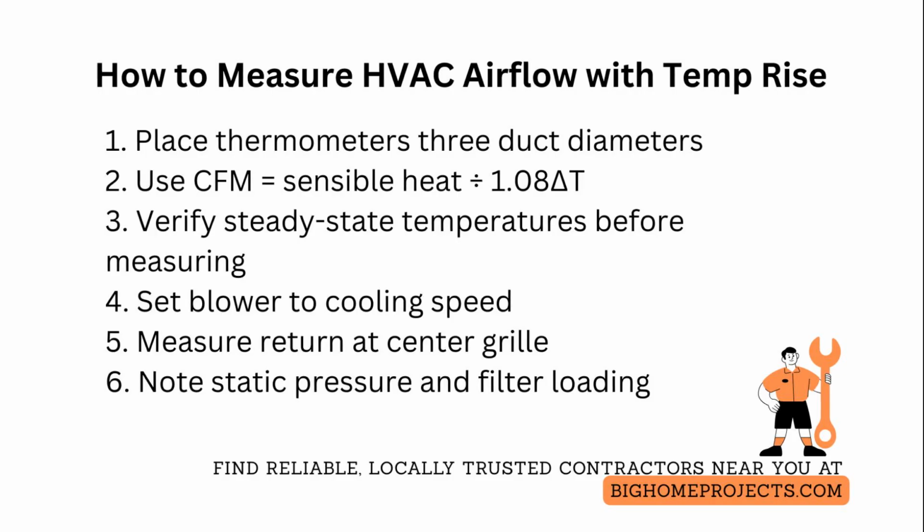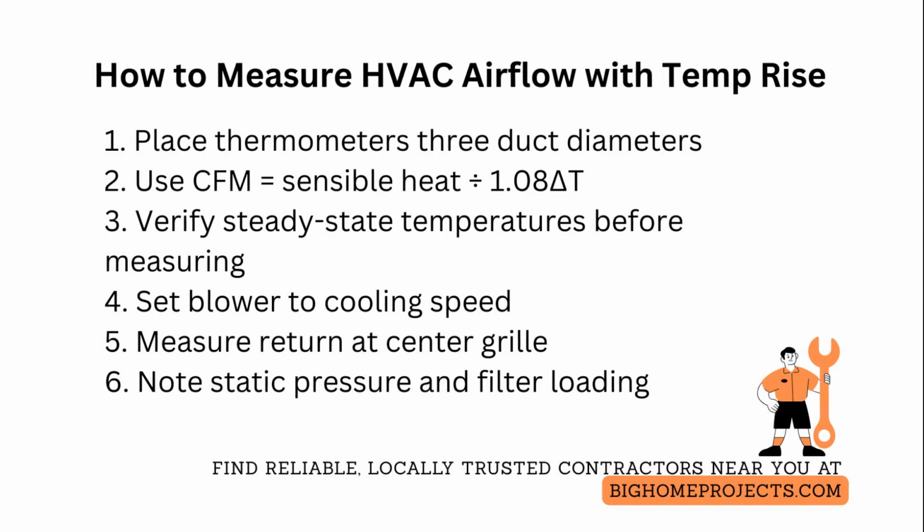Place the return temperature probe in the center of the return grill or use a well-mixed sample box for multi-return systems, and seal test doors and registers to match typical operating duct leakage.